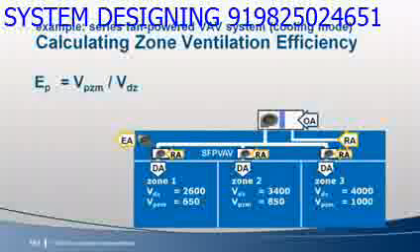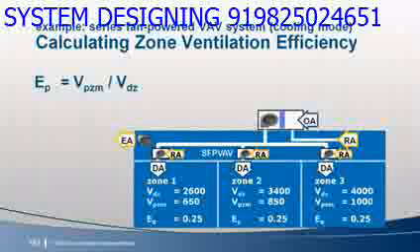For the series fan power VAV system, in our example, we're assuming discharge airflow to the zone is constant. So E sub P will be smallest when zone primary airflow is lowest. Again, we'll take the same conservative approach and use the minimum primary airflow setting of the fan power VAV box. For zone 1, discharge airflow is 2,600 CFM, and the minimum primary airflow setting is 650 CFM. So at this worst case condition, 25% of the discharge air is comprised of primary air, and the other 75% is locally recirculated from the plenum.